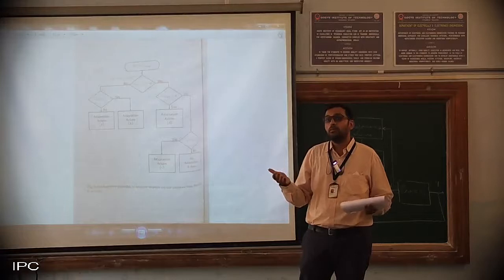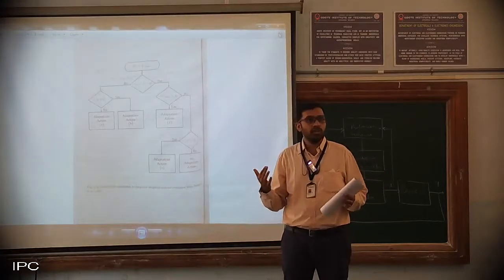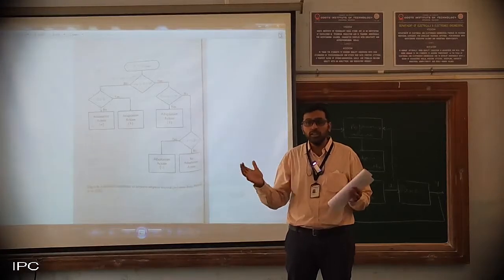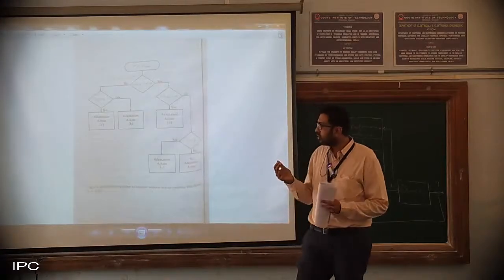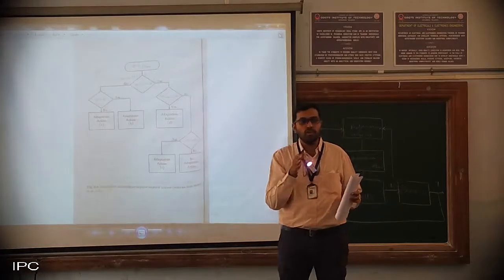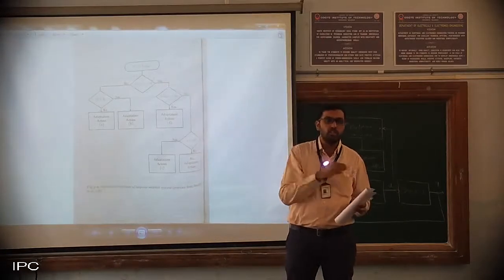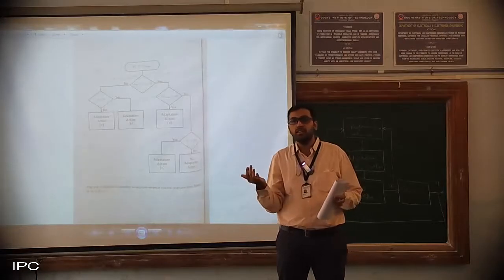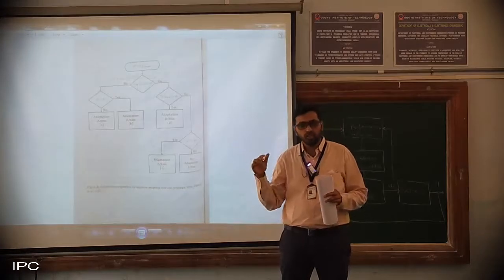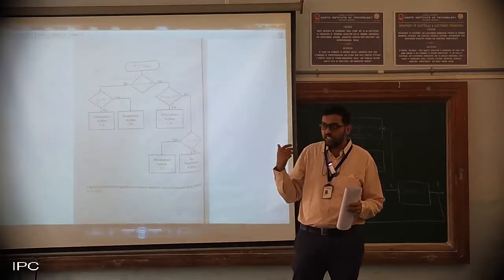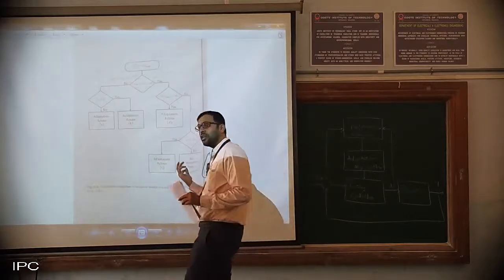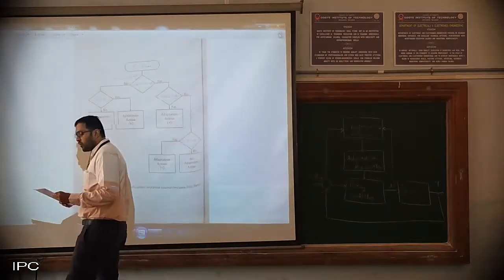Now if we are not getting the desired output, what the system does is change the shape of these membership functions, or tune the system by changing the function. For example, instead of having 0 to 10 for low, it will make it 0 to 15. So now the rule execution gets changed and the output also gets changed. By changing the parameters of the membership function, the output can be changed. So that is what we are going to study today.